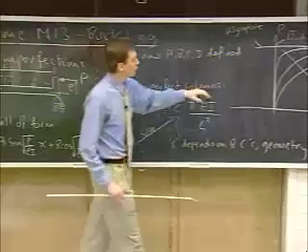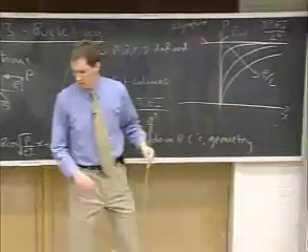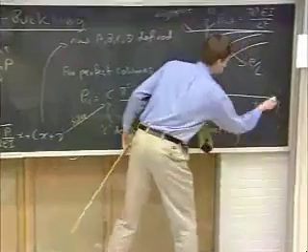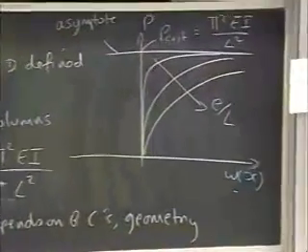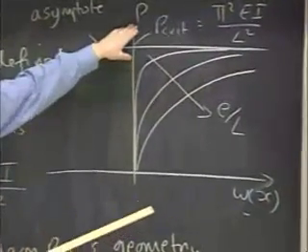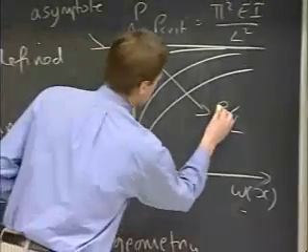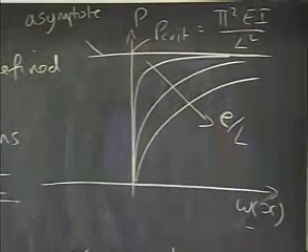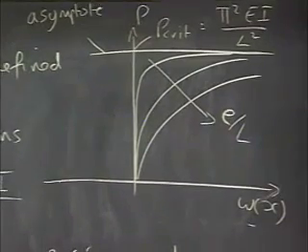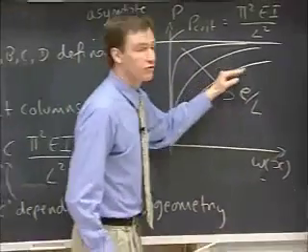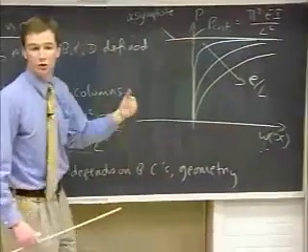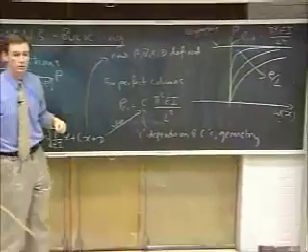And if we plot out the lateral displacement, say, of the midpoint versus the load that we're applying, as we get increasing imperfections, as this load P is applied an increasing distance away from the midline, we get further and further away from the ideal bifurcation buckling behavior that we saw in lecture M12.